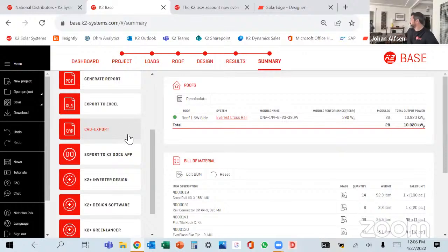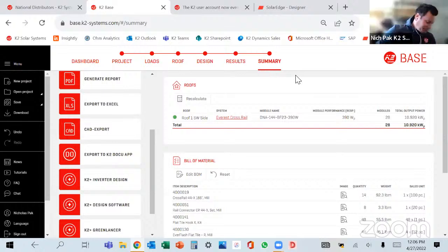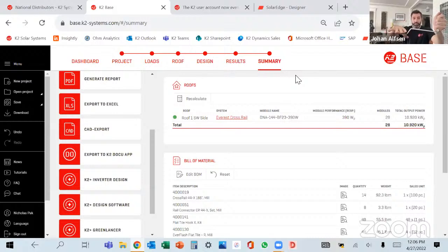But as I mentioned before, when you have that load here and your attachment offset here, you have a huge arm of leverage on there to pull out. So if you've got deck attachment, the pullout's going to be severely weakened. Shifting the load over it and having deck attached is something we're looking at right now, but not for tile hooks. That'd be for more of a standoff approach.